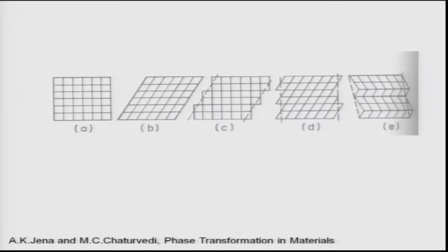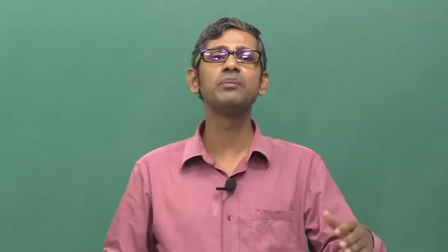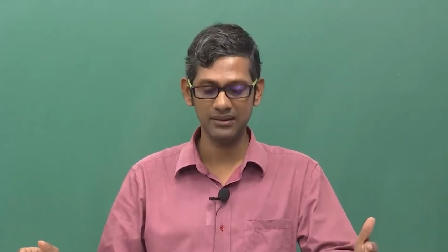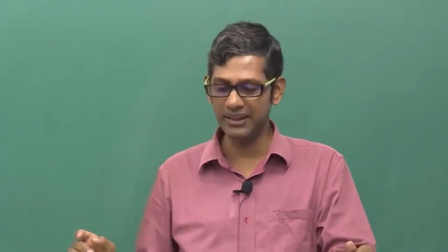You see, this is a slight plastic distortion given, so atomic planes do get moved, and subsequently these planes will be arranged favorably like that, and this will lead to twin formation. That is very evident in the picture from C, D, E. So twins in the martensite plates are actually because of this heavy plastic distortion, which is required to keep these habit planes intact. That is why this shear process leads to twins in the martensites. I hope this is clear and evident from this picture.